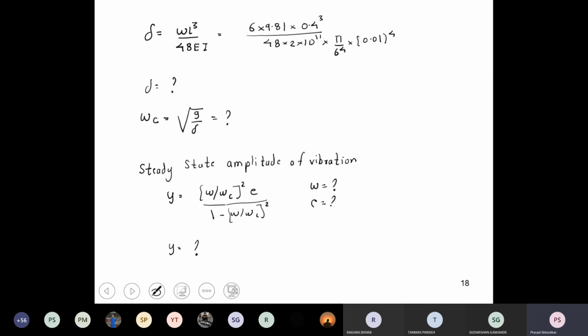Alright. Next is load on bearing. You have to calculate the dynamic load, WD, and this will be equal to stiffness K into the deflection, because the shaft is going to be deflected like this, and this is your rotor.